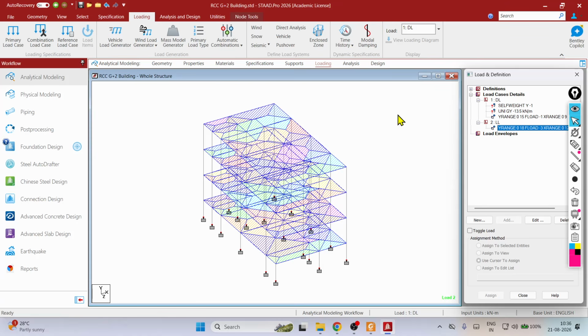Okay, fine. So for today, in case I take wind load or seismic load, we have to go with the combination. As per Table 18 of IS 456:2000, I think page number 67 or 68, the total combination is 36. So 36 combinations we have to create here. But if you take dead load or live load, only one combination is there: 1.5 dead load plus 1.5 live load.